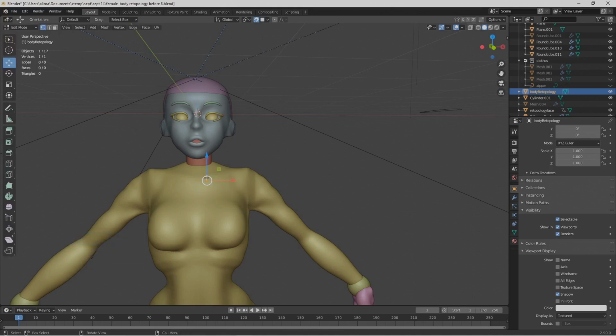So whenever you need something to snap, you can typically press G, or you can take your move tool, then move the geometry. It'll then snap to where it needs to be. So this should, as I move this one vertex up as well as down, snap right to what you see here. When I say what you see here, I mean the sculpted geometry that is the body right here. This is a separate object from this right here, which is this vertex. So we're going to use this vertex to go over the sculpted geometry to make our retopology.